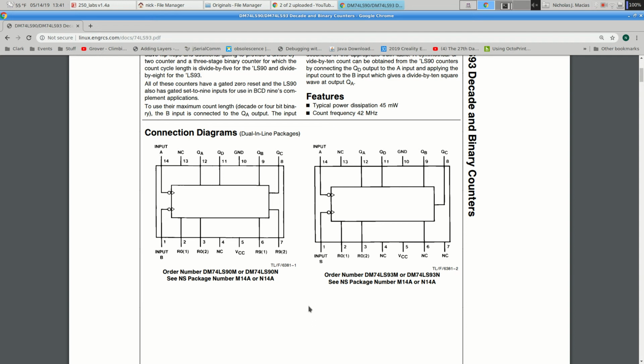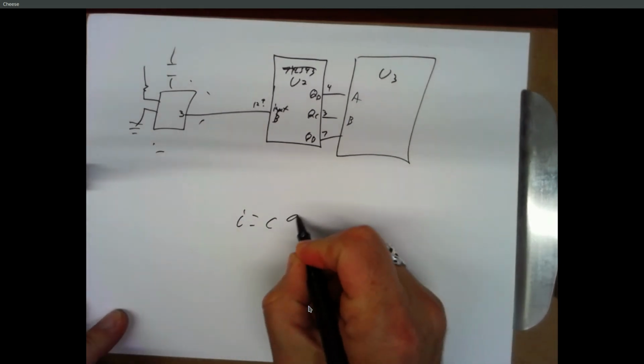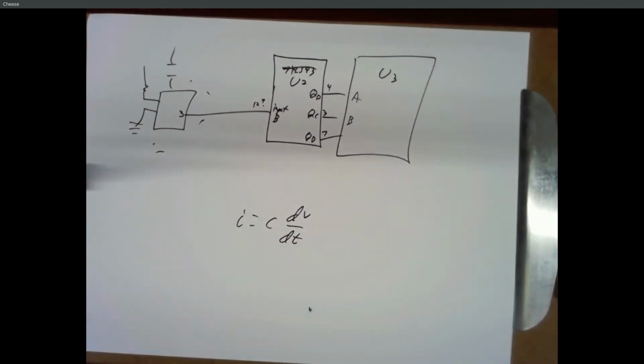So what does a capacitor actually do? Oh, in general? Yeah. Capacitors store charge, basically. I mean, they do calculus. They measure how quickly a voltage is changing, right, which is what a derivative is. But the main thing we do with capacitors is we use them to store a charge. And if the voltage is changing, it will load charge into the capacitor instead of running it through. So we can use them to de-spike circuits.